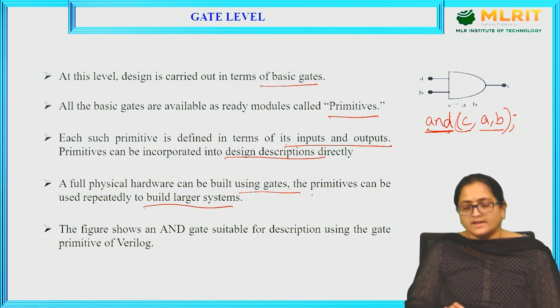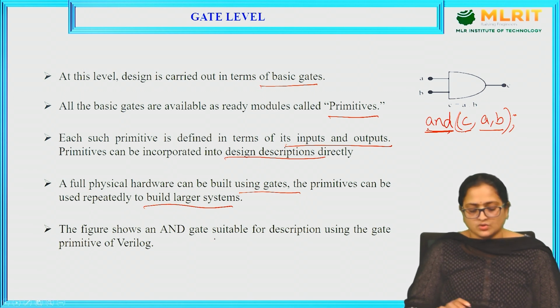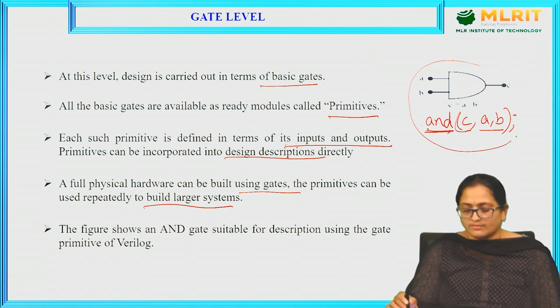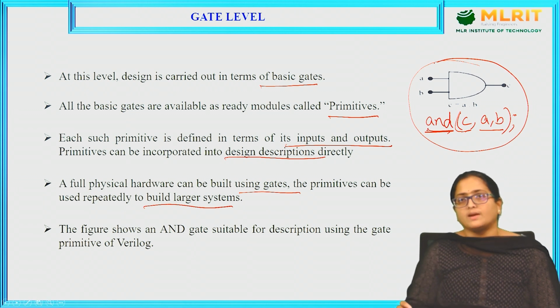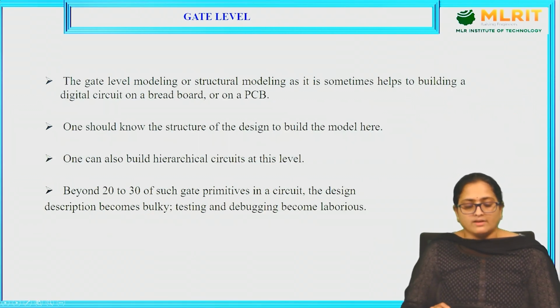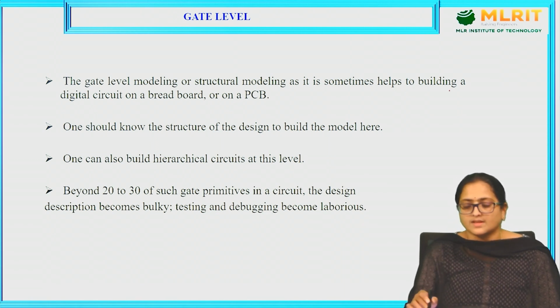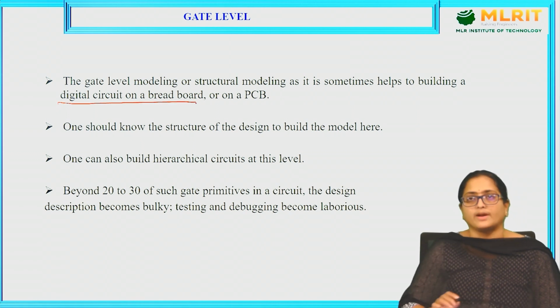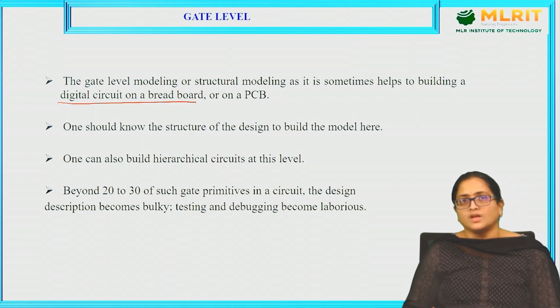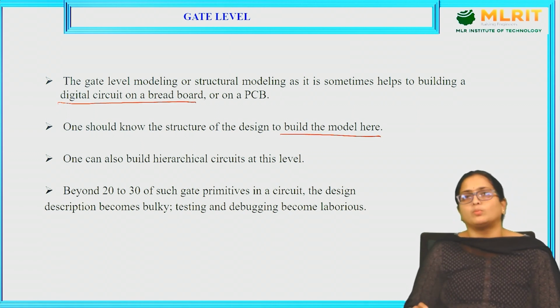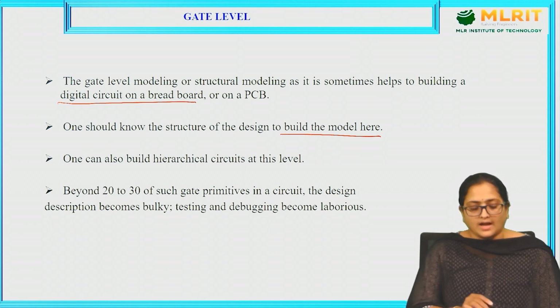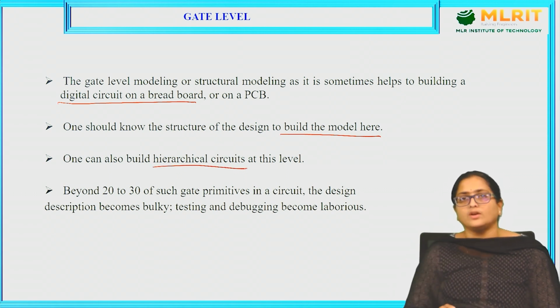If you use n number of primitives, the simulation time may increase. The figure shown, an AND gate, is suitable for description using a gate primitive of Verilog. The gate level modeling, or structural modeling as it is sometimes called, helps to build a digital circuit on a breadboard or on a PCB. One should know the structure of the design to build a model here. One can also build a hierarchical circuit at this level.